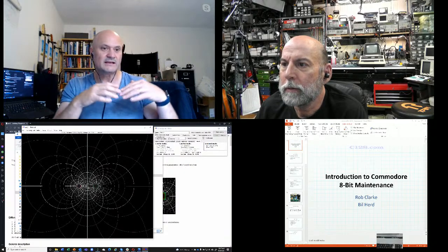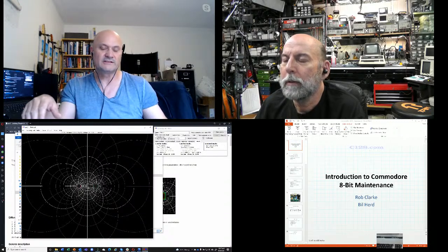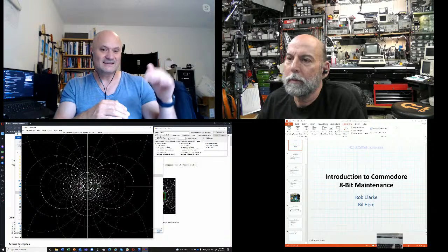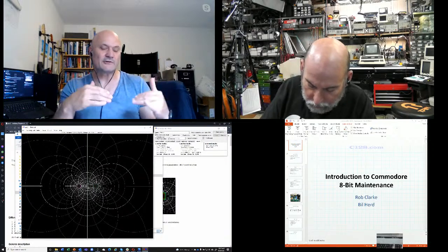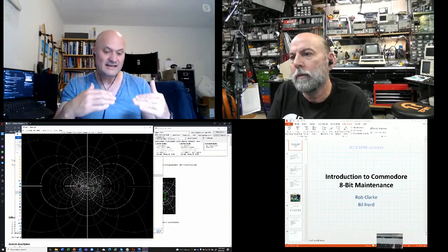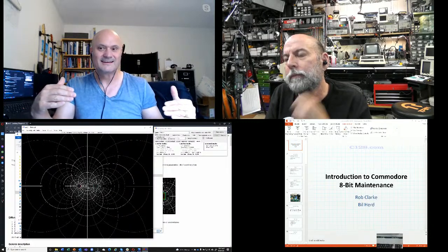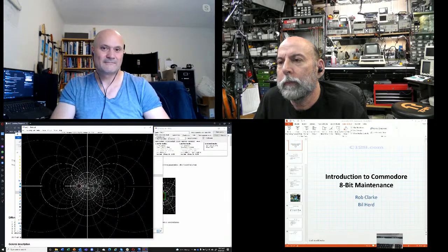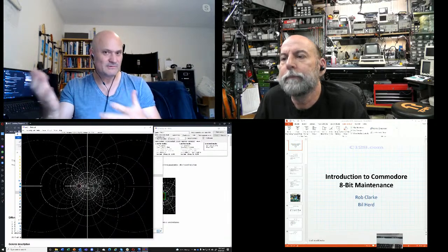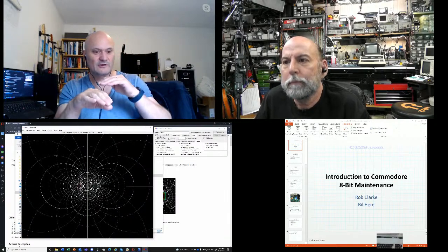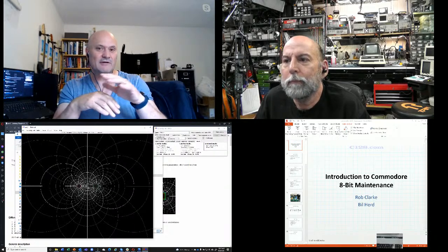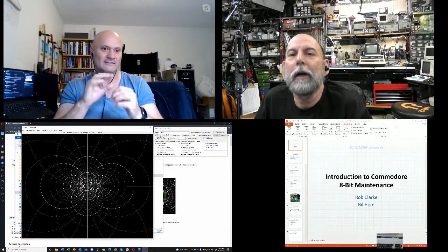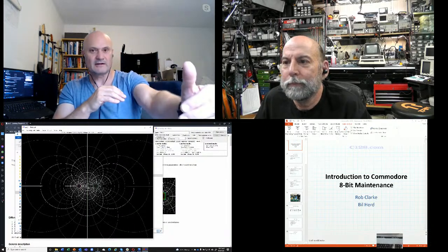It has to be outside of the ground plane region on your printed circuit board design so that it can radiate, but it has to have the ground plane region nearby at the right place as its reference. Right. So you need both, but the strip line part that makes up the antenna radiating element won't radiate if it's right over the ground plane. It's always apart from the ground plane.